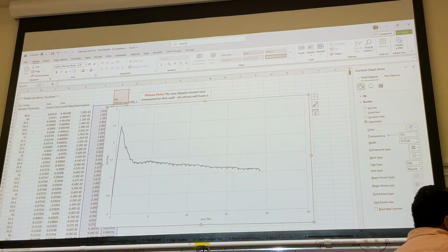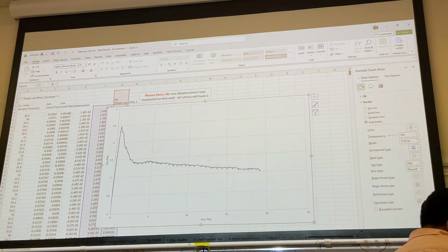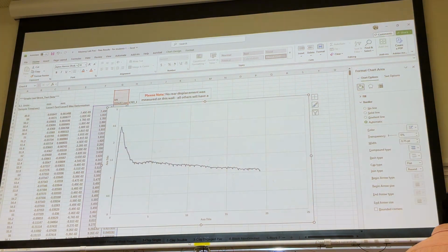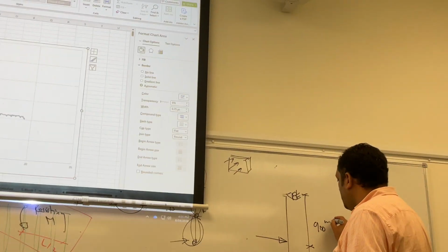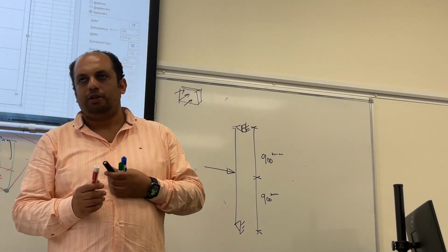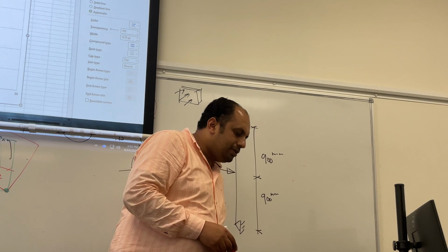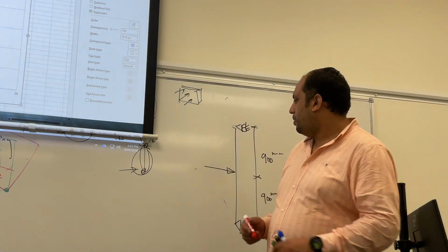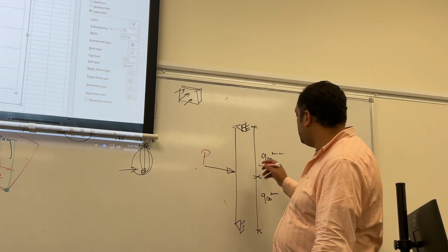So actually guys, this was our wall. Do you remember how much was the height of the wall? 1800. So 900 and 900. Because you need to calculate for the walls the out of plane bending capacity. For that you remember you need the moment applied to the wall. So this is the load P. So what is the moment? The reaction.